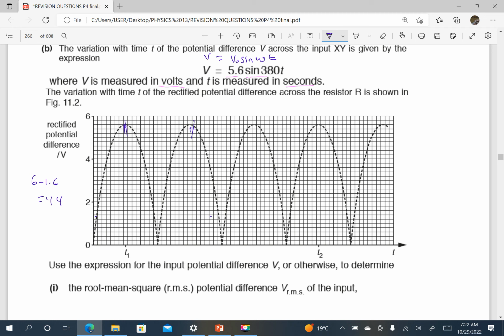The scale here is, I think, 0.2. So 4.4, these are two small squares. So our voltage should not go below this value here when it is smoothed. It's not to go beyond this line here when it is smoothed. So we just draw our straight lines. Of course, let's say we start with the charging part, this part here.